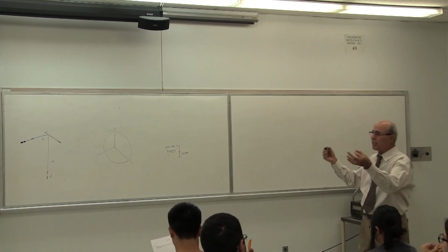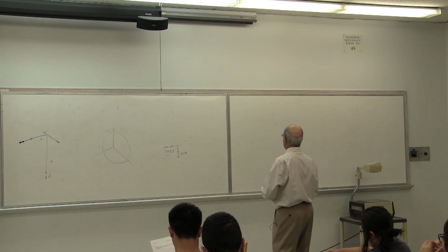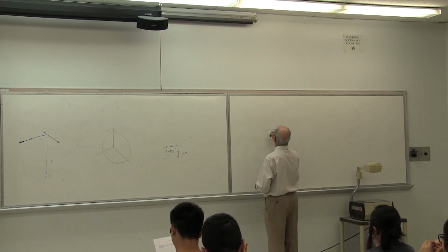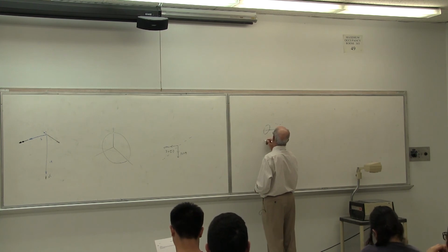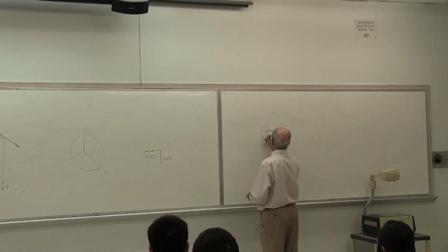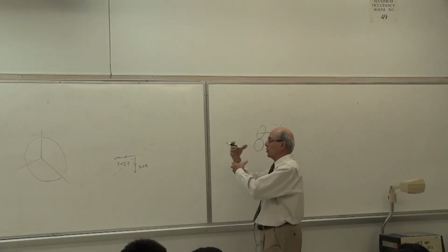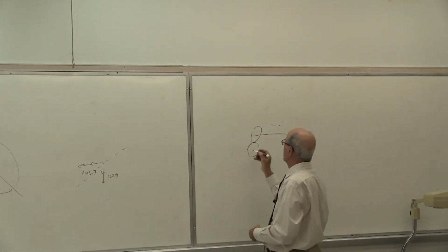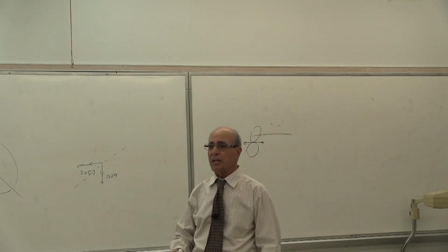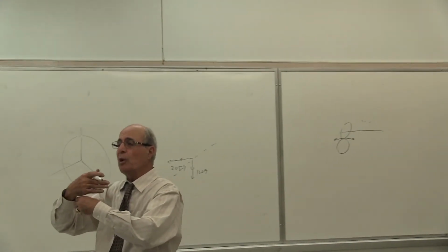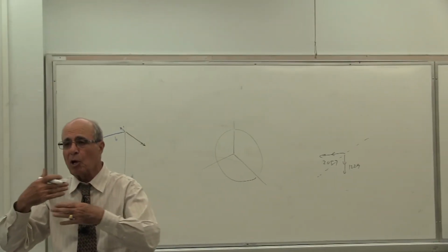So there is a middle shaft. You are designing that middle shaft. Then be careful here. If you have a gear there and a gear here, I just want to know if the two gears are on top of each other, the forces are equal and opposite. It depends where the location is. You have to consider the forces that are applied on two gears.